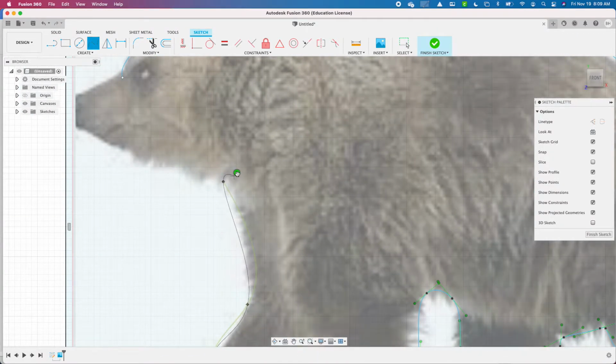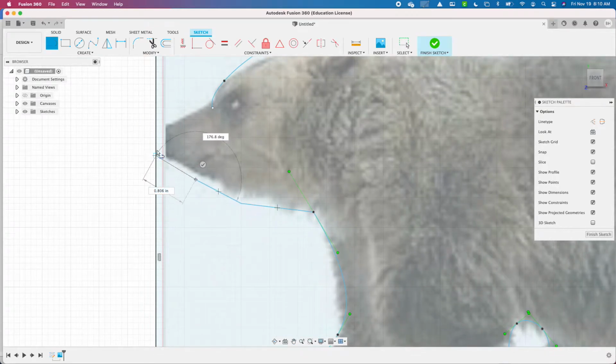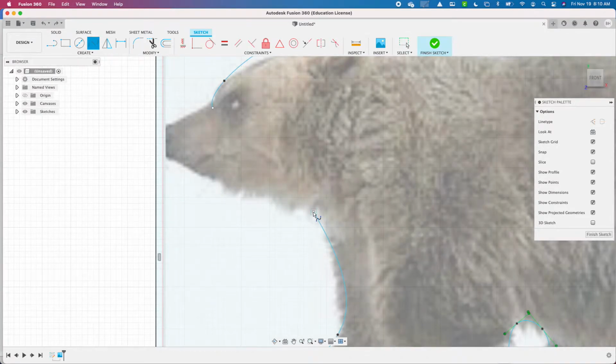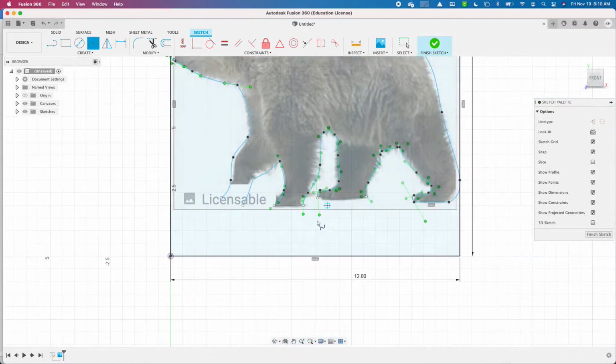and continue to bend. That's a sharp corner there, so I'm going to stop my spline and restart my spline here. And that's probably a curvy nose over there. Oh, those are straight lines. Oops, and then go to a spline here and curve around this and ending right there. I missed a little section here. I'm going to go back and use a straight line.